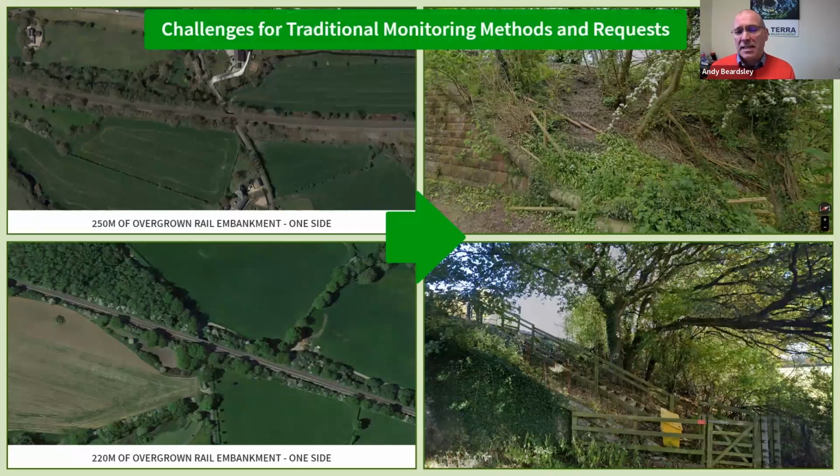So, to move on to some of the disadvantages of geospatial monitoring of rail slopes. Once the baseline coordinates or levels are recorded, there is only a monitoring comparison when there is a revisit. That might be weekly, monthly, quarterly, etc. This means collapse, trends, fluctuations, or weather-related events are completely missed. Data comparison is usually a manual spreadsheet exercise and not easy to interpret. This, compounded by the large time frame between measurement visits, makes an exercise that is basically ineffective in most cases.